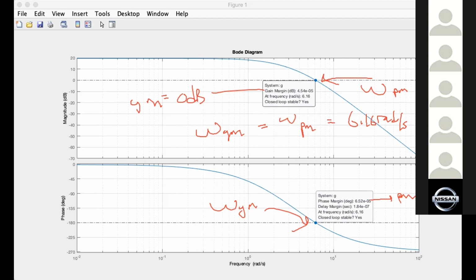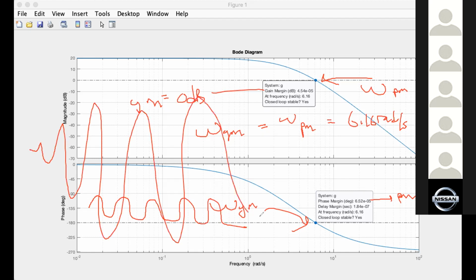But I thought, Doctor, critical means it's the most stable it can be. No. Critical means that the response is swinging. The time response is swinging constantly. Then when it becomes unstable, the time response will be like this, becoming bigger towards infinity. Stable means the response goes up with overshoot, then goes down, then it's stable like that. This is stable, this is good. This one is not good, this one also not good. It alerts that the system will become unstable very soon.